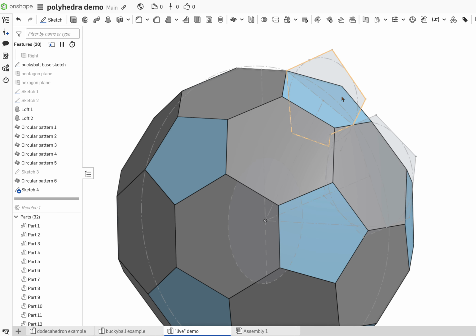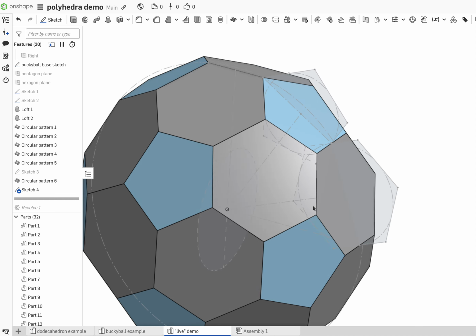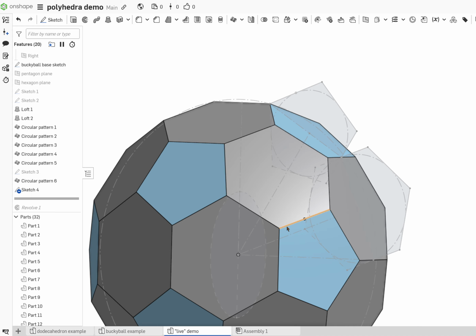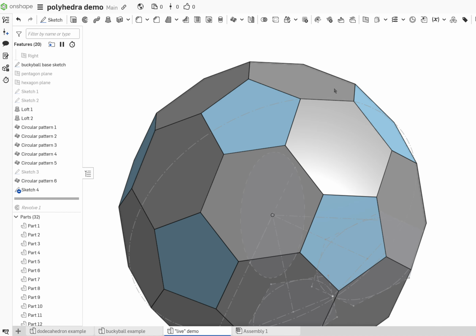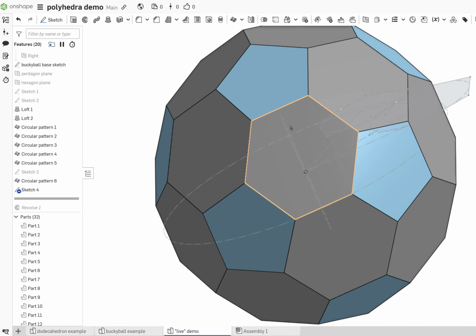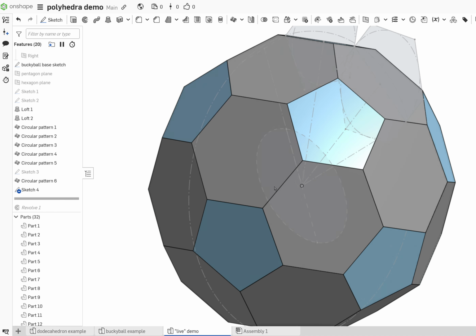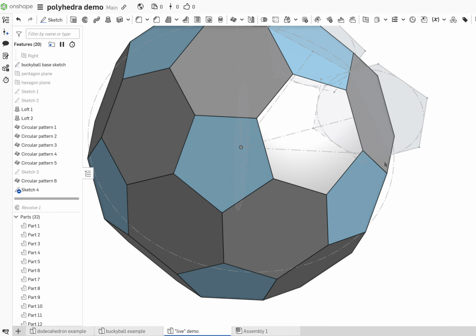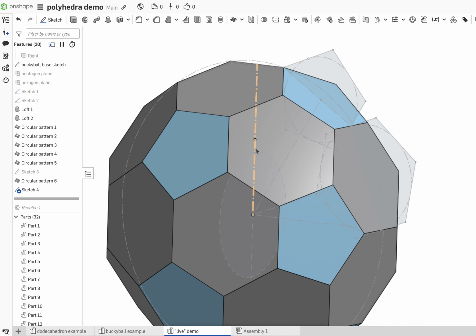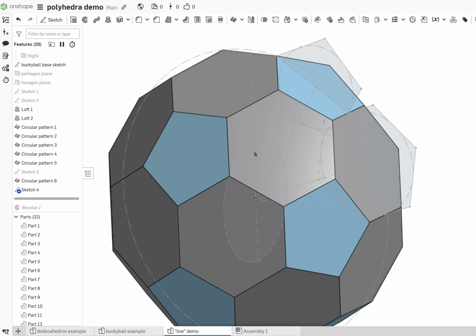As long as your faces are normal to the middle of the face, to the origin, you can do this. I think this is way easier than doing it using angles. And the angles route just doesn't work. If you try to do this with angles, you'd look over here and all these angles are self-intersecting and exploding. So it's a little abstract. It's a little different than what you're otherwise going to do, but I haven't seen any documentation of this technique, and this is just what I do now when I make dodecahedra.